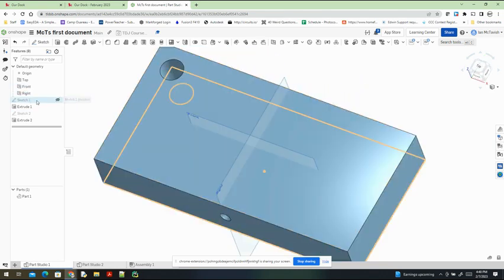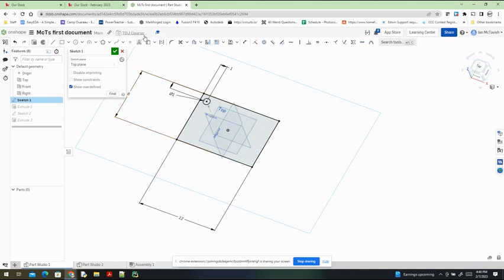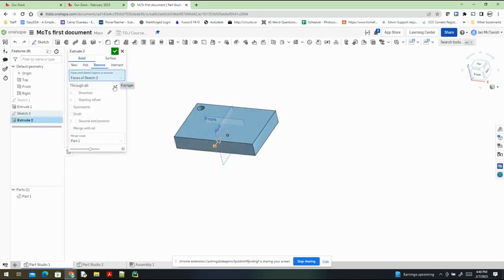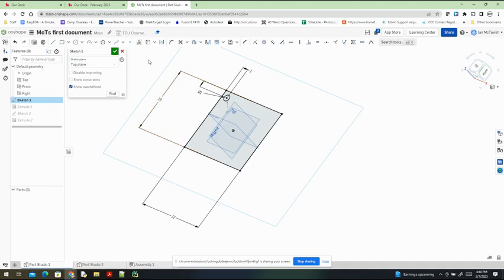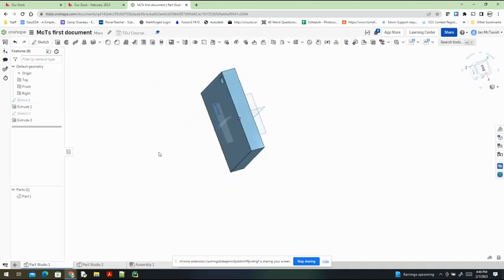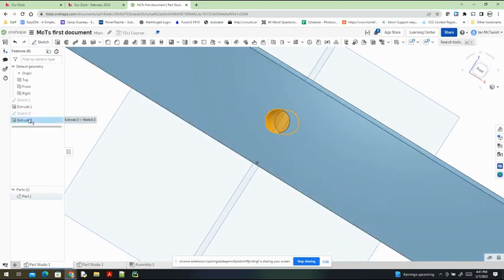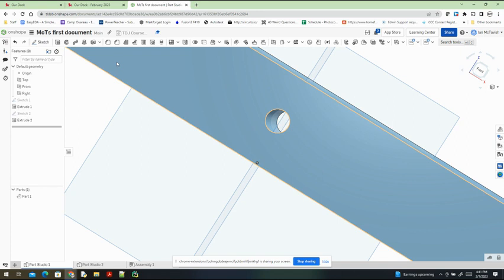And the bonus with this is that if I go in and change my dimensions, so let's say it's 6 inches, let's say I'm going to change it to 8 inches. That hole is right there. So if I go back here and instead of through all, let's say blind and I select 8 inches. Now, because that's 8 inches, there's the hole. But if I change that dimension, and so instead of 8, it's now 10, you can see the hole no longer goes all the way through. And there's the end, 8 inches away. So that's why using through all is a really powerful tool that allows you to have it go exactly where you want it. So that's the goal with this.